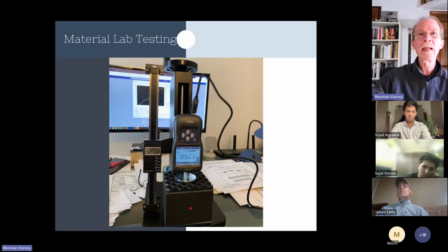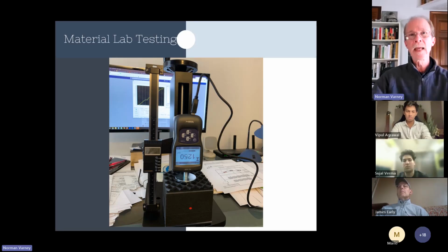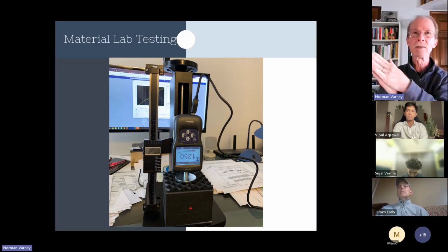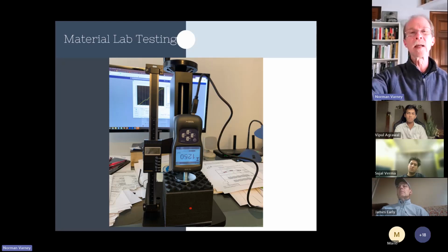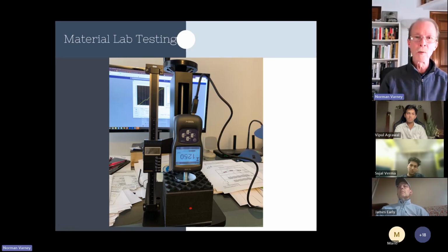So whenever we play any music with 70 hertz, which is like any music you would play, it's going to resonate and it's going to act like a capacitor. It's going to take that energy, store it for a moment, and release it later in time. And so you've got now loudspeakers playing after the original event has stopped. So time smearing, added resonances, and buzzes and rattles too.